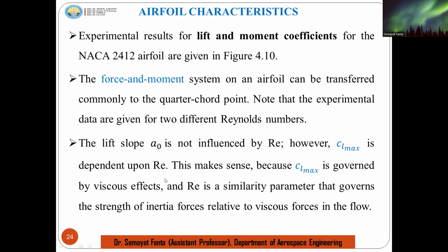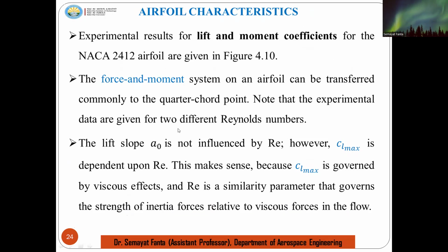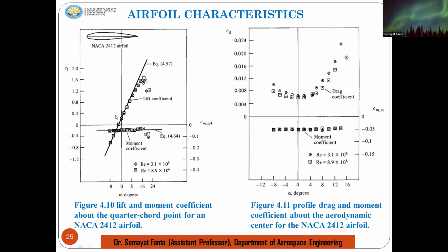Experimental results for lift and moment coefficients for the NACA 2412 aerofoil are provided here. This is a cambered aerofoil, because the 2 in 2412 indicates the camber. So it is not a symmetric aerofoil and it has a nonzero alpha value at zero CL.